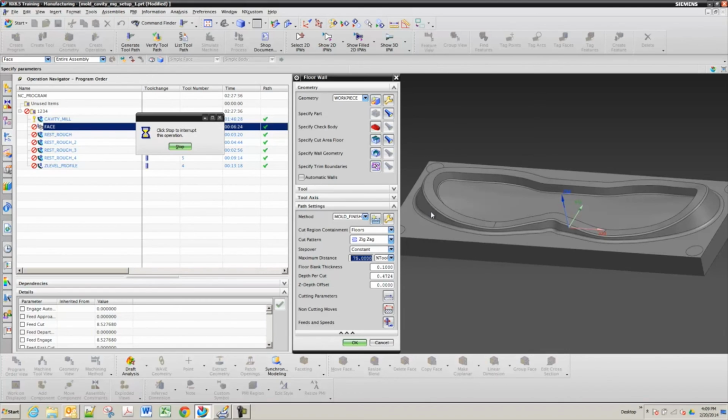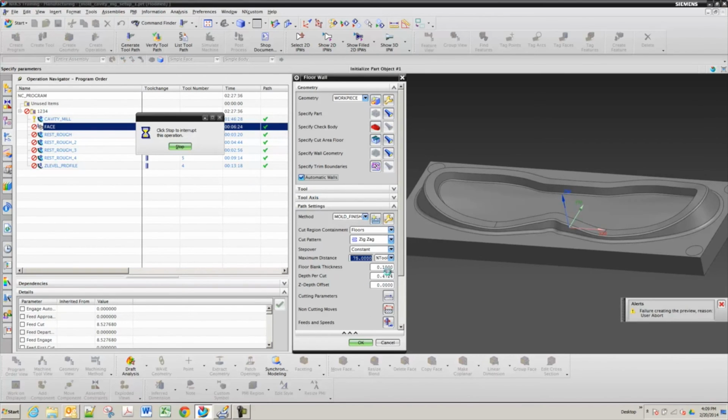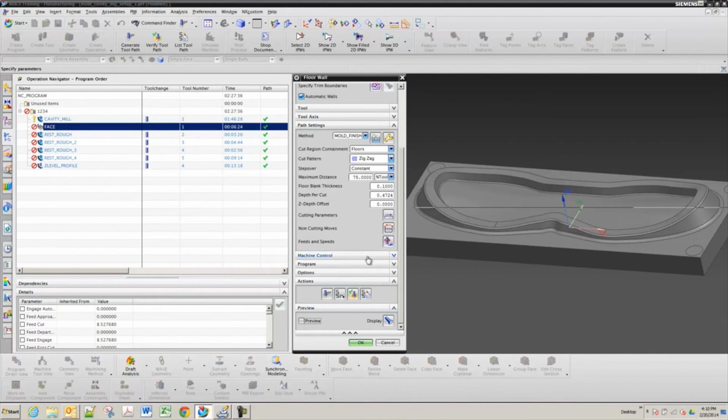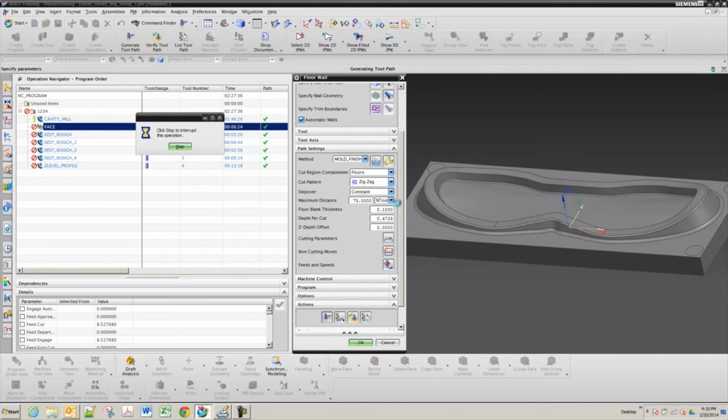And for this case, because it's a standing core rather than a cavity, I'm going to turn off the preview. I hate that. Go down to the bottom. They really shouldn't make that preview a default. Okay. Alright, so we'll just generate it and see what it looks like. Normally you'd want to keep it similar. This is kind of a different style, going from definitely a cavity to kind of a combo cavity core. There's going to be less fixing the more similar, but because we had a flat face that was above, the part was below it, so I'm interested to see what this one does. And why is it taking so long?